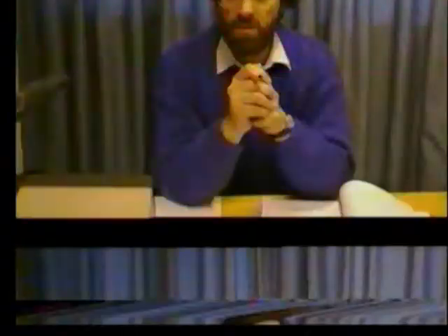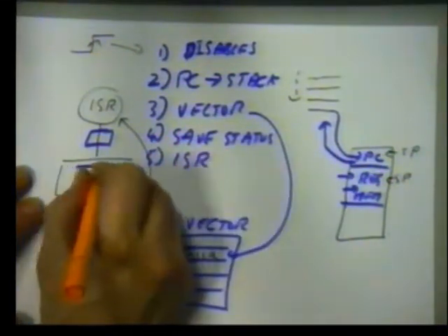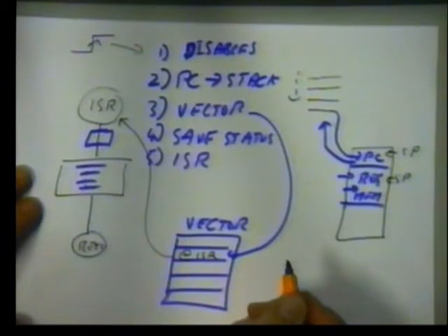Only you know which bits of the processor you're going to use. So before you use it, you have to take a copy. You push all the contents of the registers, the flags, the memory you're going to use onto the stack. And now that you've taken a copy of everything, because you're very good and clean, you tidy up after you go. Only now can you actually execute the body of your interrupt service routine.